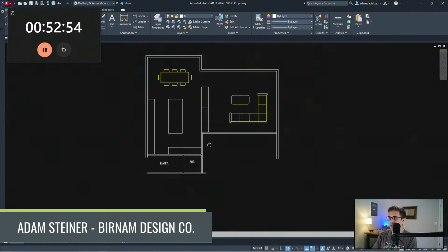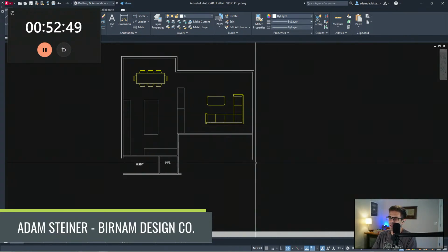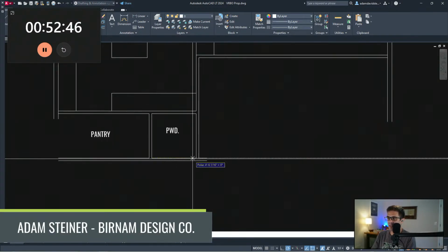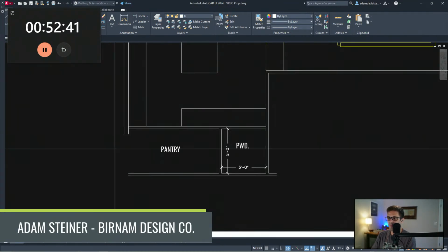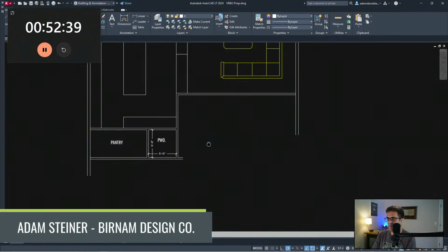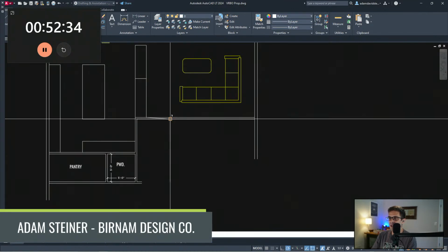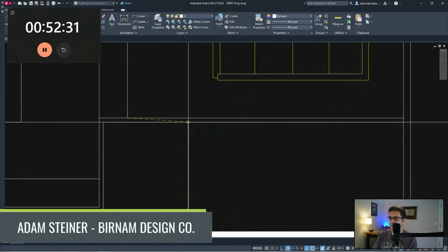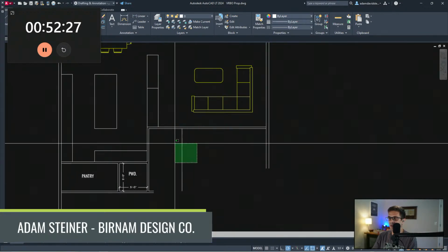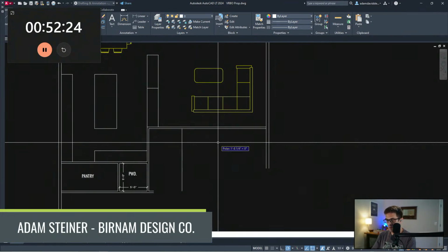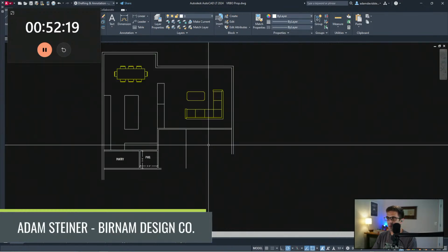If you're the type of person that really wants the extra feeling in your spaces, I'd go slightly bigger, 6 by 6, but that's a good size for most. Most, not all. But most of my plans have a 5 by 5 powder. Let's show 6 foot of foyer. I think I want a little bit more than 6 foot of foyer because I'm thinking about the main sight line to the great room, it's only 3.5. So let's maybe make that an 8 foot foyer. Then we could do a double door on it too, which could be cool.